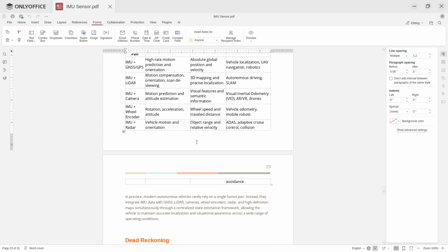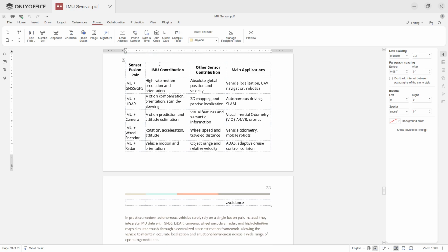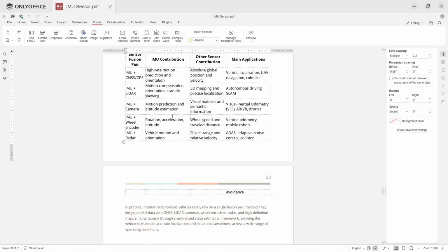So one thing you have understood is that the IMU helps to find the next state, right? It has three things: accelerometer, magnetometer and gyroscope. The accelerometer will give you acceleration, so with that you can find different parameters. If you integrate acceleration, it actually predicts motion, right? So let us move ahead.